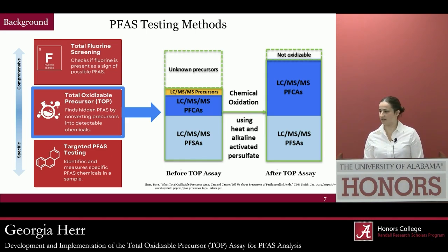Do we have PFAS regulations in the U.S.? Yes, we do. So for drinking water, in April 2024, the EPA released the first round of PFAS drinking water regulations, which regulated 6 PFAS. So we're currently in the period leading up to compliance enforcement for those. However, in May of 2025, the EPA announced that they are intending to review and revise these regulations. So although these regulations are definitely in flux right now, we do see a movement in the U.S. towards more monitoring and more regulation of these chemicals.